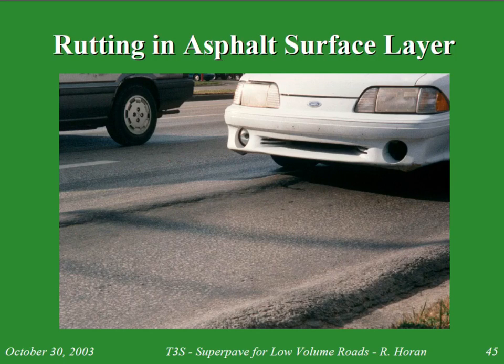And the third, of course, and I don't have a slide for this, maybe I should, but the third main conclusion of the SuperPave program was that you could see some type of spider or alligator type cracks occurring due to fatigue loading. Okay, so due to very high loads on your pavement over cycles of loads. So these high loads occurring over a long period of time in a repeated fashion, so in a cyclic fashion, you start to see these type of alligator cracks, almost like spider web type cracks that occur in the pavement. All right, so those are really the three main conclusions that came out of the SuperPave program as a result to asphalt type roadway failure.